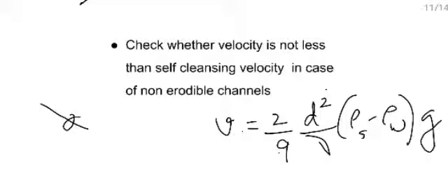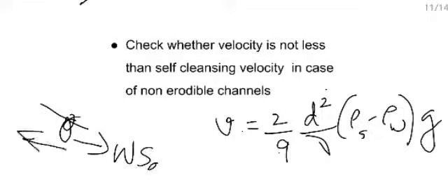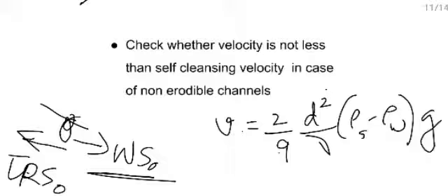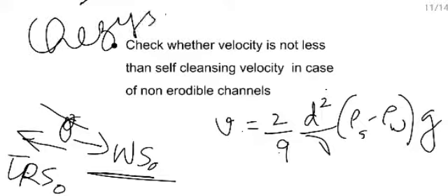Okay, now another thing is this particle experiences weight times slope, and the shear stress is the factor that holds it behind, tau r is known. So this should be high so that it moves with the flow. Based on this and the natural flow Chezy equation, which is another equation like Manning's equation, to describe open channel flows.